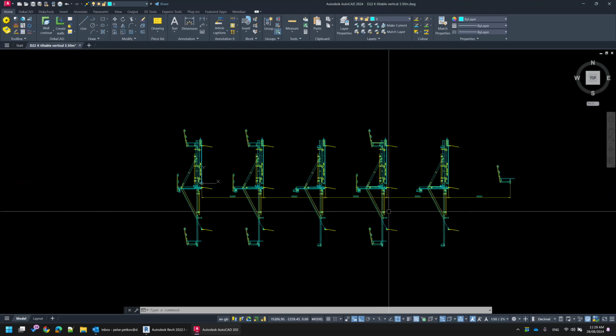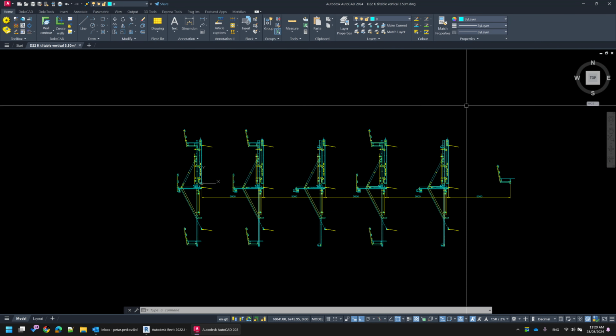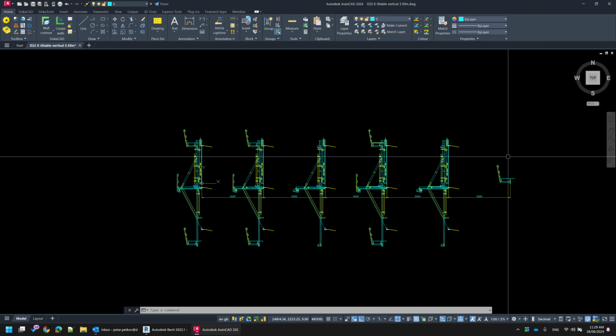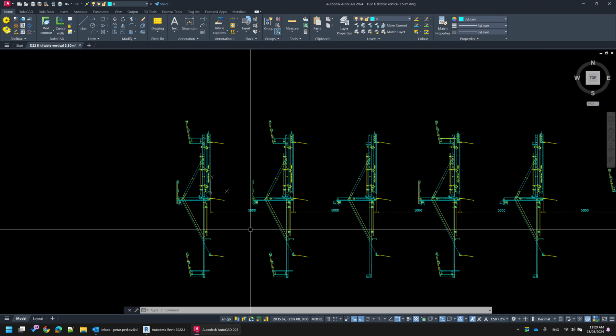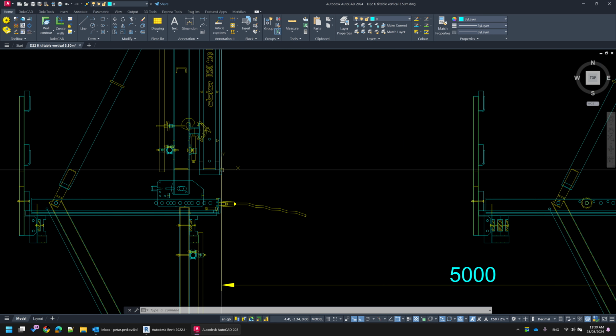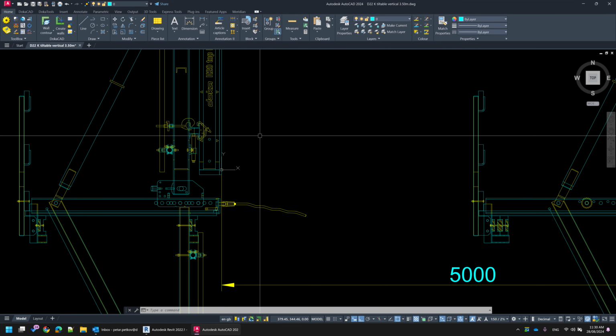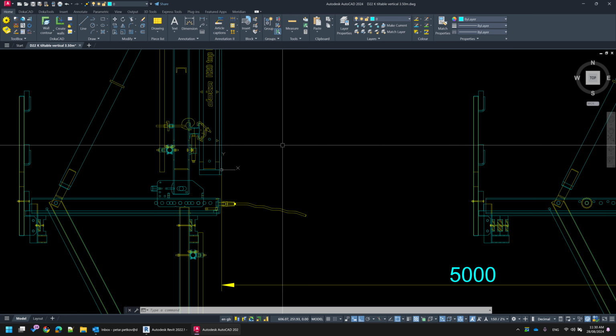The first thing is, if you want to save time, it's nice to open multiple sections in the same drawing. Once you do, arrange them so the insertion point of the first one matches the insertion point of the file, which will help you put it in the correct insertion point in Revit as well.